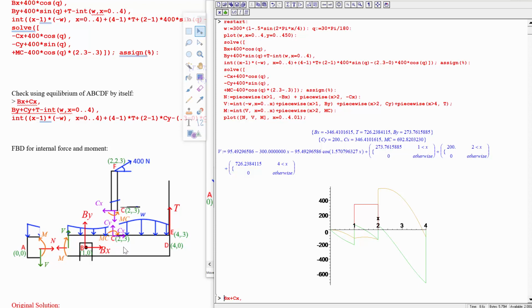the shear force assumes that we didn't have any kind of point moments applied from an x force there. This basically creates an extra moment from the 0.3 up from the center line displacement that it's at. So that means that we need to add that in as well, not just mc, but plus cx times 0.3. That, like mc, is going to create a moment that spins this in the clockwise direction. So we have to add that as well to get the moment graph to line up. And there it is.